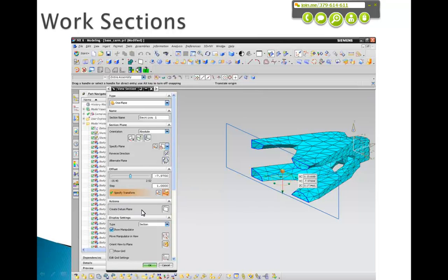And the way you do that in NX is you click this button that I'm hovering over right here, which will create these blue curves as permanent section curves, working curves, but you're going to want to create those and keep them on a reference layer.